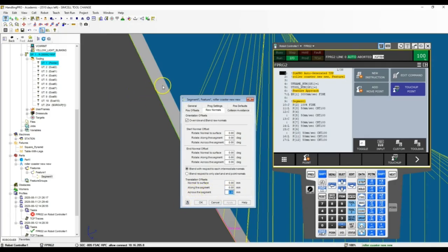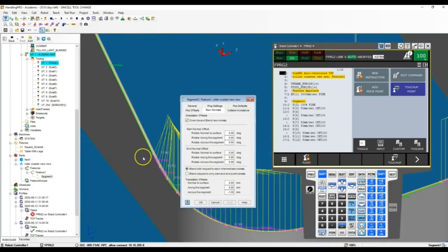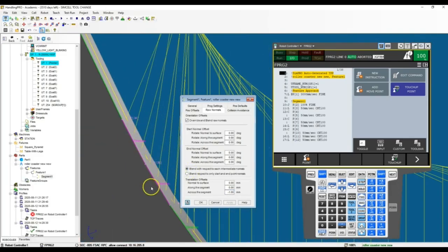These are 2 millimeters deep. So we're going to just go 1 millimeter for the center. And you see that if it goes the wrong way, just put a negative symbol and it goes the opposite way. So now the path is down the center of our part.